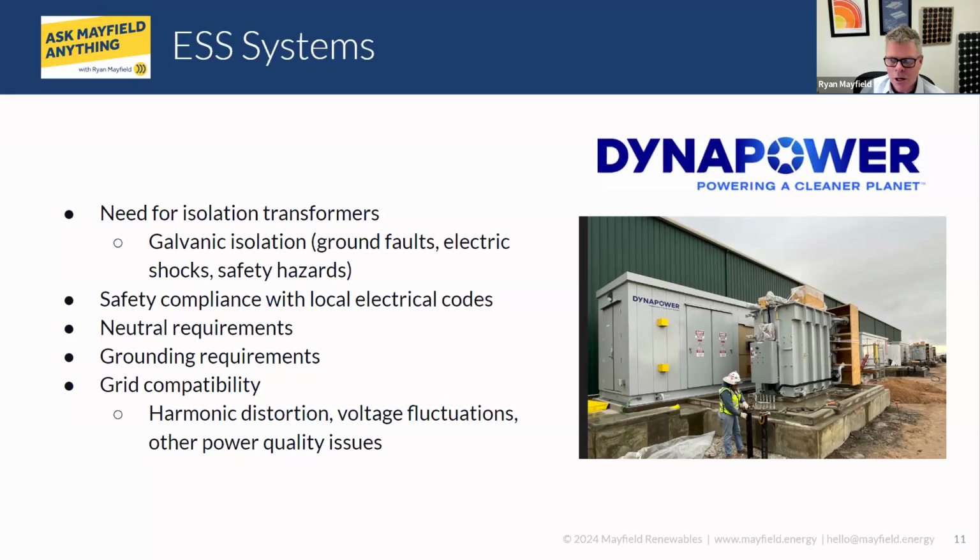Very interesting. That's correct. I'm just looking at the slide, and I purposely put harmonic distortion and voltage fluctuations there. And I'll go back to where my expertise lies. Those are the large industrial systems that we have, depending on the transformer and rectification elements and groups and the number of pulses that the rectifier is supplying on the DC end.